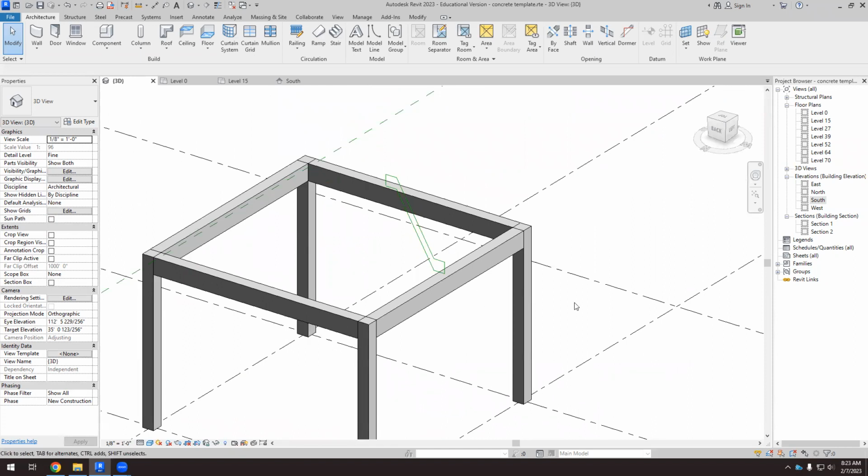So what we are going to do now is to sweep this shape. And we need to find a path, and the path is, well, they are the beams. So we have to select the beams to create the path, and then we have to select that shape to sweep the shape around this path. Okay, I'm going to do it because I think it's easier doing it than explaining it.